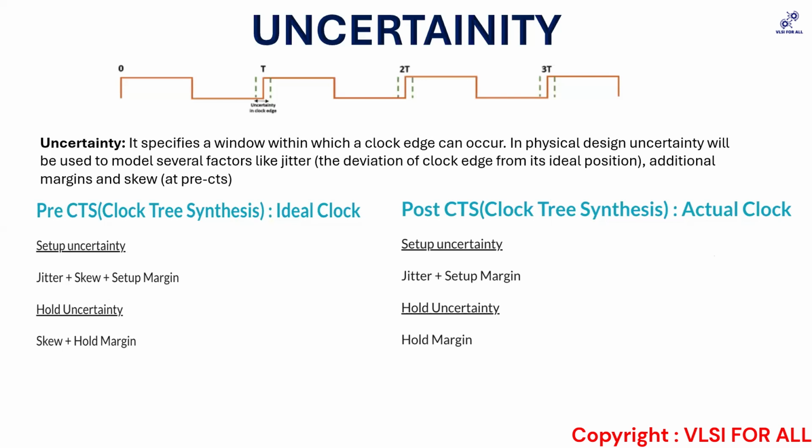You guys always mug up everything. I have looked at a lot of folks; I have taken the interviews of 100-plus folks. Setup uncertainty value is always greater than hold uncertainty. When I give you a question or play with timing diagram related stuff, this is where people fumble up.